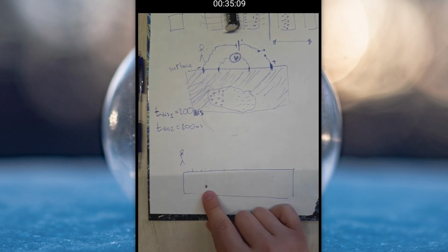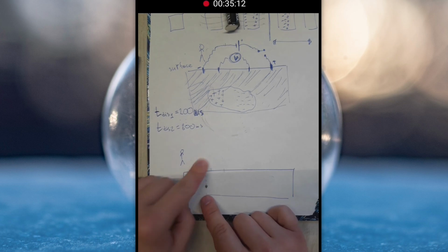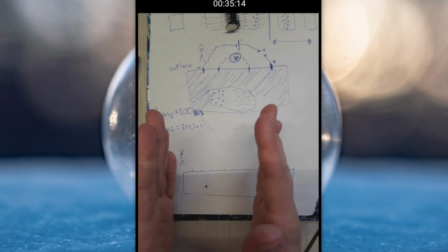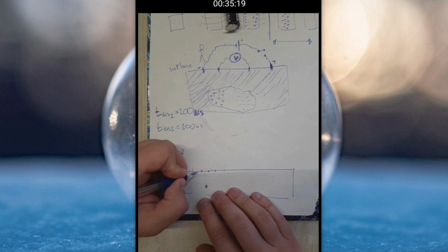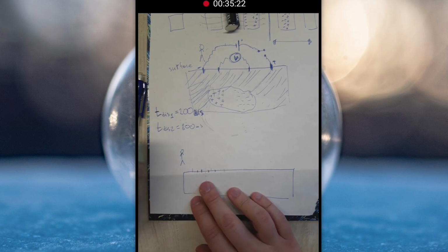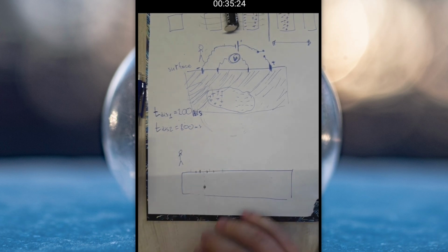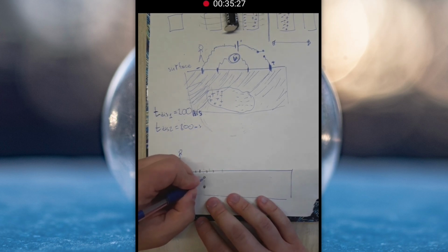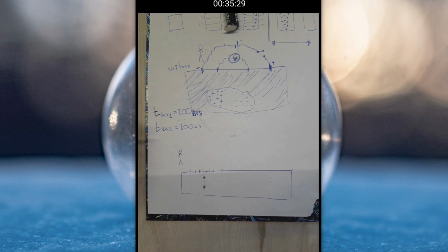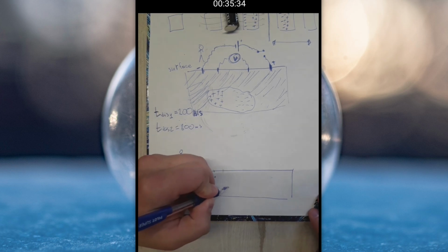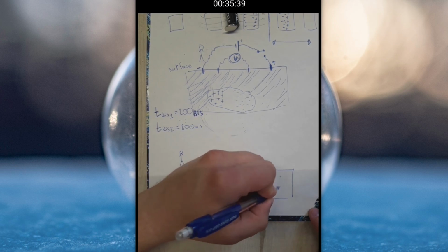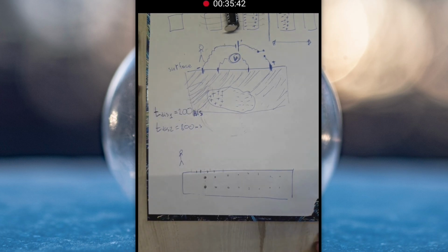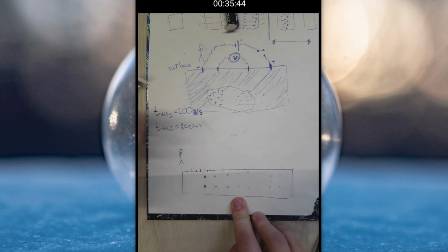Then we measure this exact point, but we measure it slightly higher by narrowing the distance between the electrodes, like let's say here and here, right? Those are two new sets of electrodes. It means that we are measuring our time to discharge in this point, and then we do that with the whole area. Yeah, just a cross section. We can do this for the areas as well, and we get a heat map.